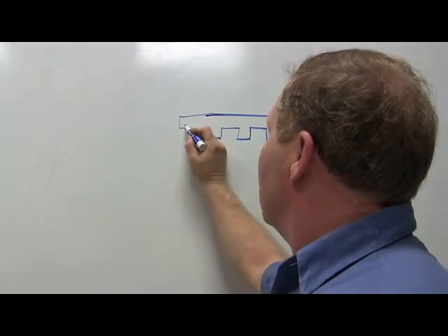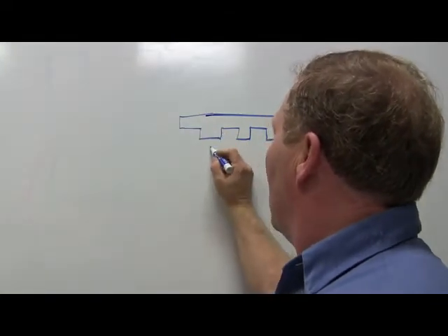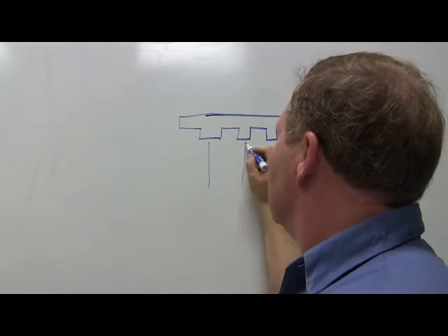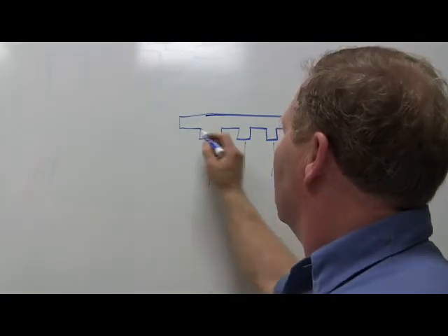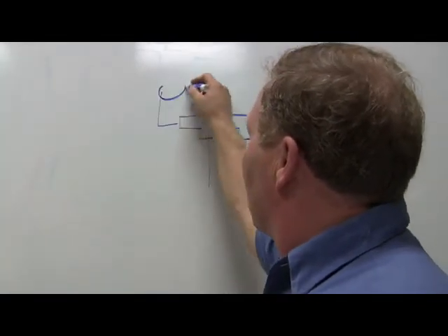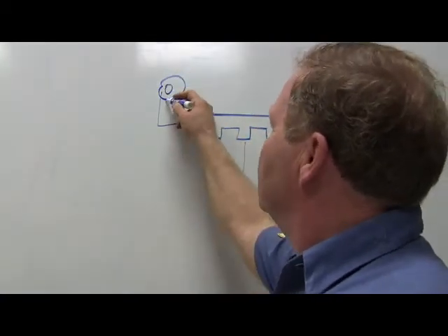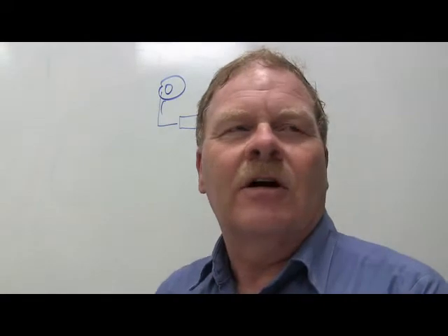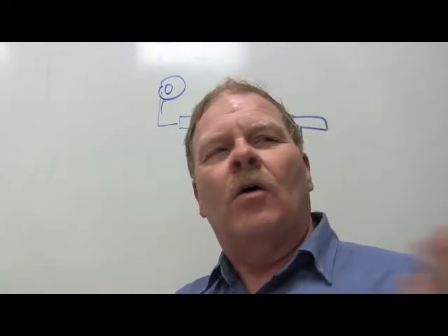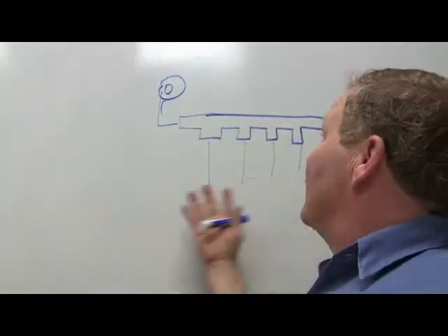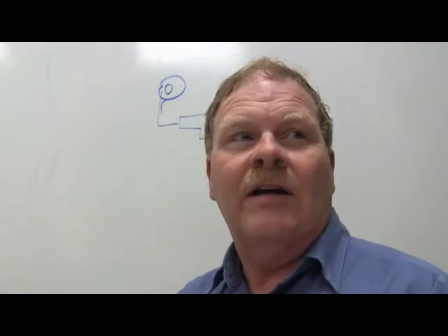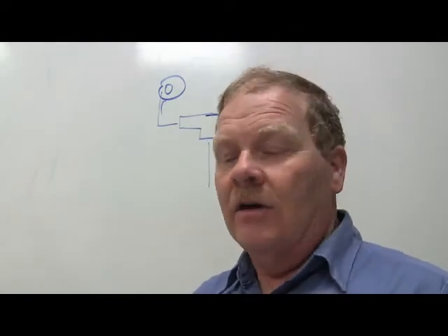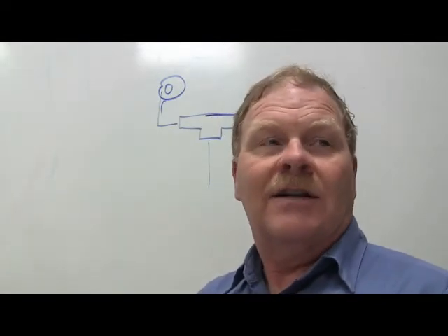And you're basically going to have a whole bunch of ground wires going to this and hooked to a major ground wire, which is hooked to the frame. It's a strange thing, but if you've got 5 or 6 grounds that you're going to run to the same thing, having 5 or 6 grounds going under an eyelet on a post is kind of dumb.